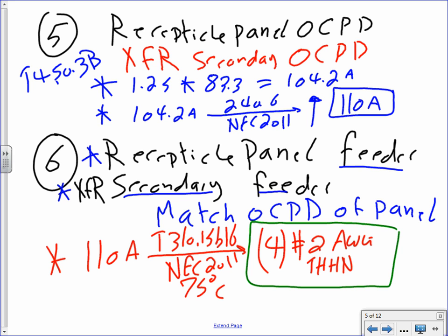Up to 300 to 400 amp, especially receptacle panels and lighting panels, guys, full neutral is a good design to accommodate harmonics. You start derating the neutral if you go higher than 300 to 400 amps. That's what starts making sense. So we're not derating the neutral at the receptacle panel. A lot of computers, full neutral, safer. Could I have derated the neutral? Yes, if you know the neutral load and there are no harmonics, but there's a lot, so full neutral.